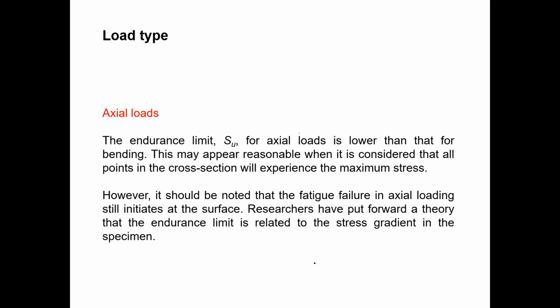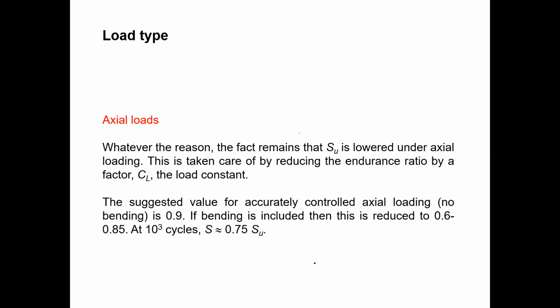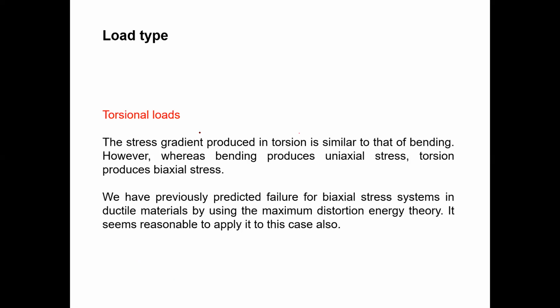So you can apply axial load. There are different kinds of load type: axial load and bending load. For axial load and bending load you can use the same theory. It's not too much different. So same theory you can use, no worries. 0.9 SU, 10 to the power 3 cycle. And torsional load will be different, so you need to consider a different aspect.